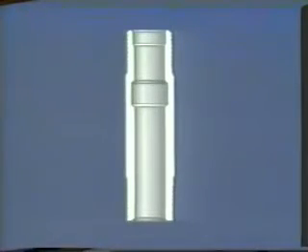Downward jarring secures the locking dogs in the profile of the nipple. Upward jarring then shears the pins attaching the lock to the running tool and releases the running tool from the lock. The no-go nipple designed to be used beneath the W1 selective nipple is the D nipple, whereas the Otis uses a bottom no-go design with a no-go restriction located in the lower end of the nipple. Camco uses a top no-go design.